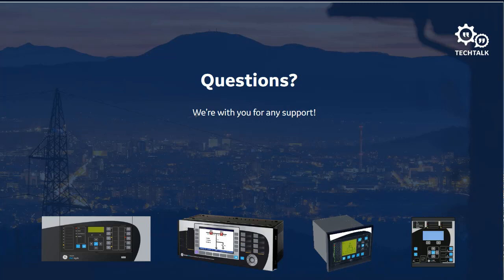If we know the fault type, we've probably got enough information to calculate some of those other quantities. If we know the positive sequence and it's a phase to phase fault, we've also been given the negative sequence, and the 0 sequence is 0. The negative sequence is equal to the positive sequence for a phase to phase fault. So for fault currents, if we know the fault type and we're just given the positive sequence quantities, we could probably, in most instances, calculate negative and 0 sequence.